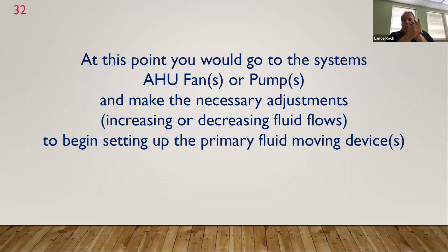You have a chiller at massive amps, and you have a simple thermostat that needs to be satisfied. So there's usually an air handler with a supply and return fan feeding the space with the sensor that also probably has pumps circulating water flow through the coil, chilled or hot water. You then go and take that chilled water and you have secondary pumping systems. You might have a tertiary system, secondary pumping systems, flowing water, that's horsepower. And then you have your primary pumps at your chiller. Again, we have horsepower. Then you have the chiller itself and additional pumps sending condenser water to the tower and the fans on the tower themselves. So you have a lot of energy usage.